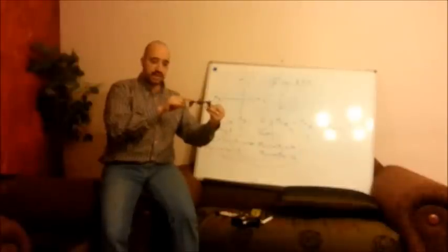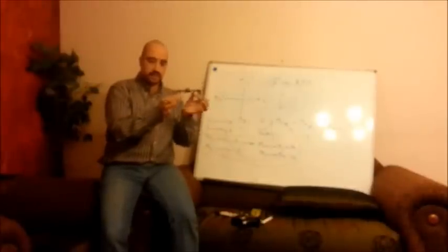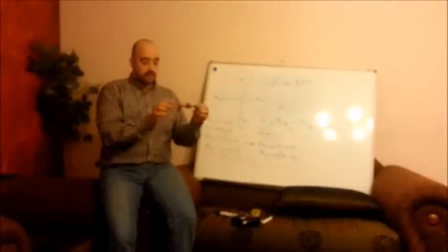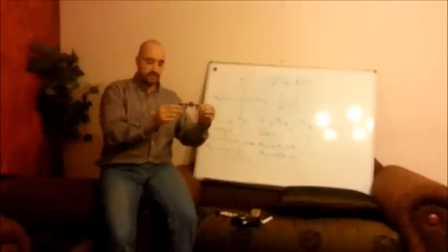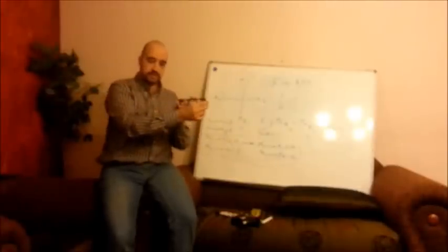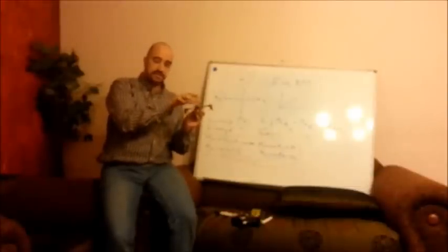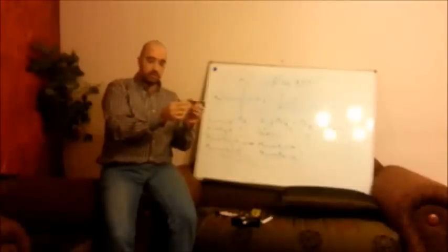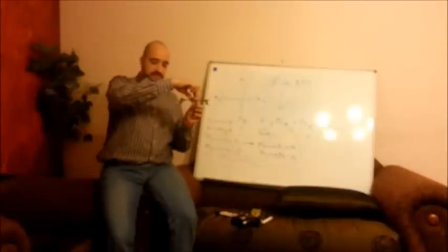So as long as these motors are balanced, the quad is fixed and doesn't rotate. Now, if we change the motors that affect the rotation in this direction, by decreasing the RPM here and increasing the RPM here, the overall effect is a force that makes this quadcopter want to rotate like that.